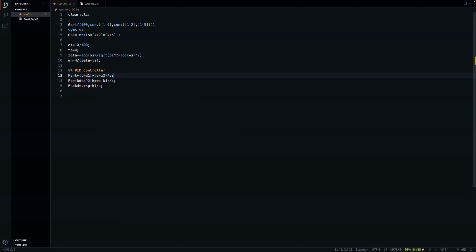Then you end up with a new root locus plot, and then you can conclude what k value you need in order to assign the pole. But here, first of all, Z2 needs to be written down like conjugate Z1 if you're talking about a conjugate pole pair. So you cannot have two different complex numbers. They should be conjugate pairs. So that kind of creates an issue. But for now, I'm not going to bother with that, but I'm going to use this representation.